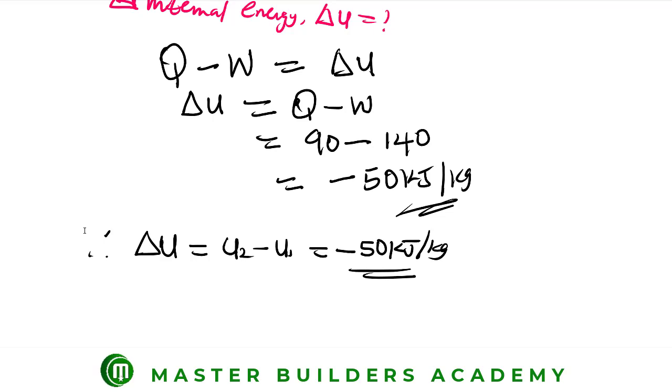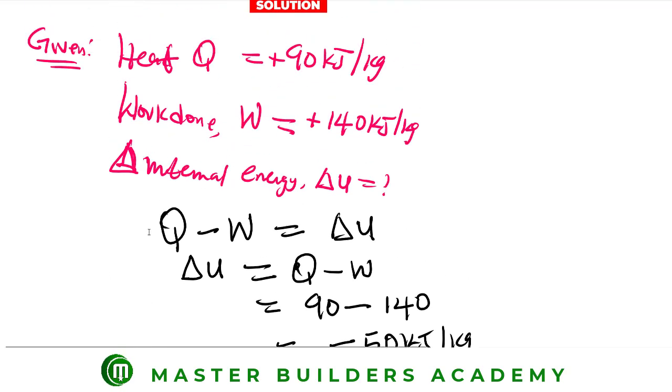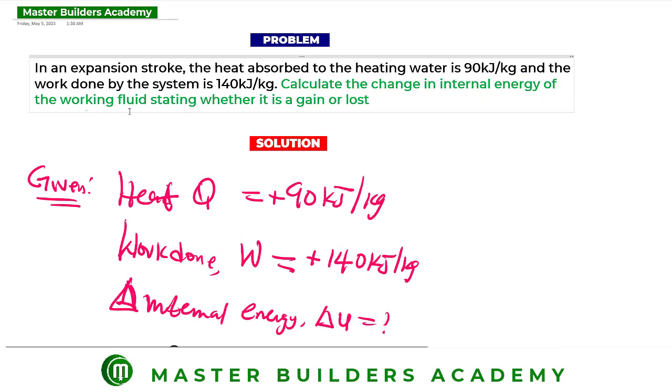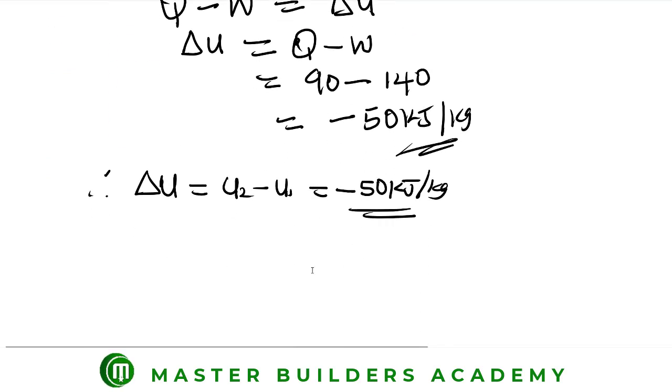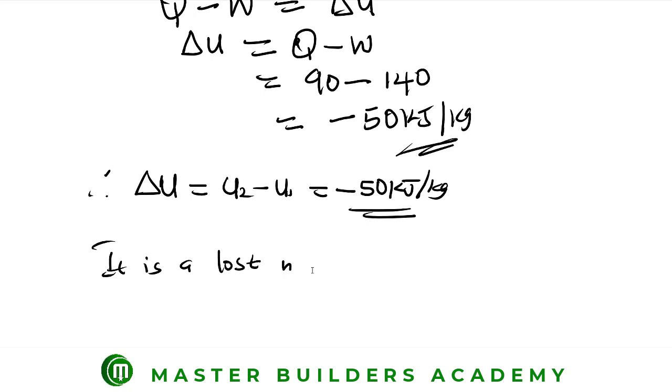But this is not all to this question. We were also asked to state whether the fluid gained or lost this internal energy. Is this internal energy gained or lost? As we can see now, because the value we have here is negative, that means the internal energy is lost. So we can therefore state that it is a loss in internal energy.